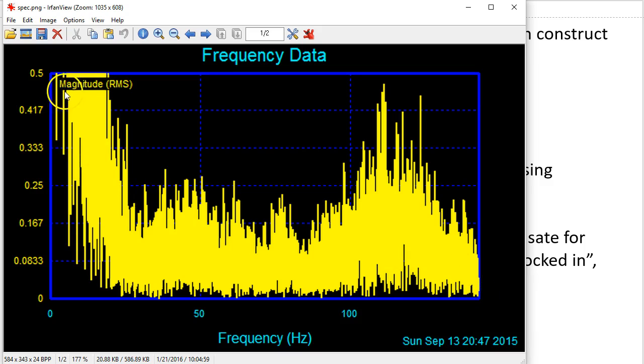And we can see that here down in the, say, 20 Hertz and below range, there is a huge spike of data going off the top of the chart. And that is the actual copter motion, that is sort of what the PID loop is flying based on. And this other stuff here, everything up through, like right here at around 125 Hertz, that is probably a harmonic of the prop fundamental frequency, right? And then there's something down here, right? So this is all just noise and vibration that the PID loop still has to be aware of, but maybe